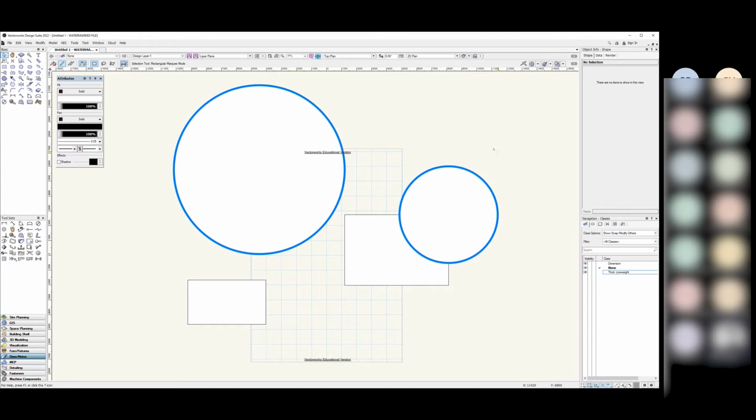And it means that if you're using classes as you're drawing, when it comes to the end of having a finished drawing, when you want to print it out, if you realize that actually my line weights for my walls aren't quite right, or maybe I want to rescale some hatches or patterns, you can do that super fast simply by adjusting your classes. So it's a really useful one to know. So I'm just going to give you a couple of minutes now. I want you to explore making a couple of classes.